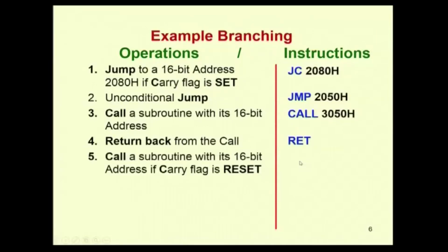The return instruction and call instruction can also be conditional. For example, you want to call a subroutine if the carry flag is set or reset, that is the carry flag is 0, no carry.